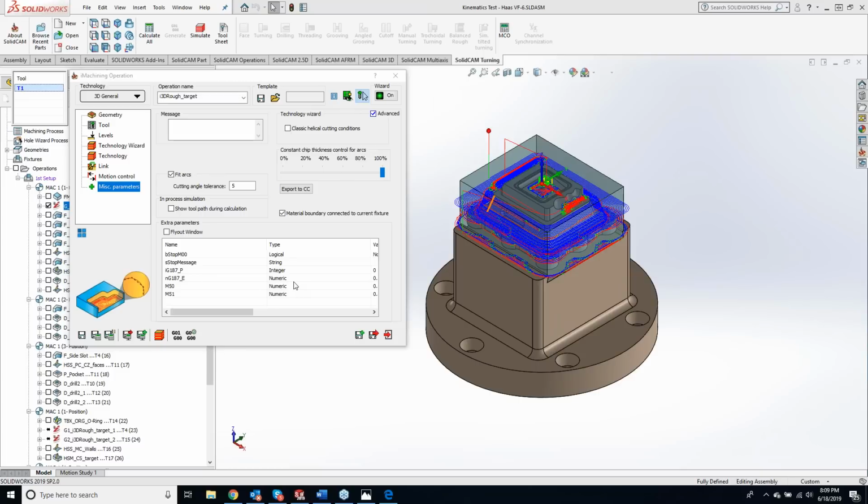And in there, you can actually set the different tolerancing. So it's not going exact point to point, but it's rounding as it's going through. So like what Greg was saying, when it has to make that switch over, it does more of a rounding in there. And that's just a Hurco miscellaneous parameter that I can remember of right now.